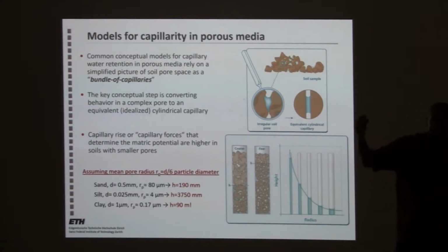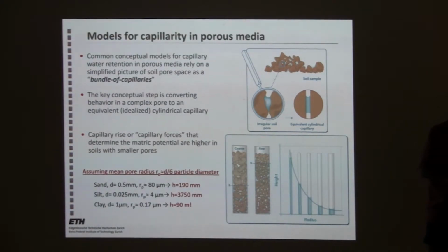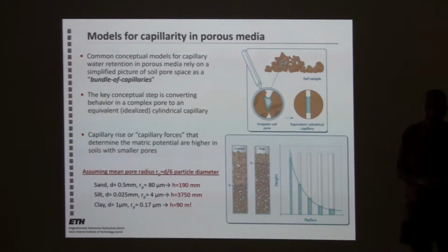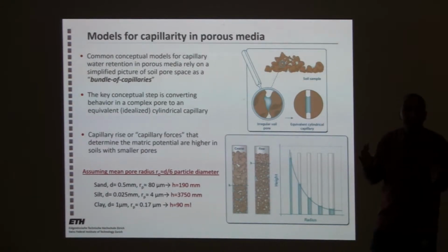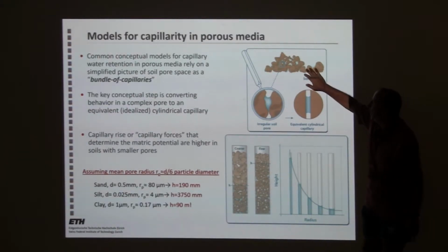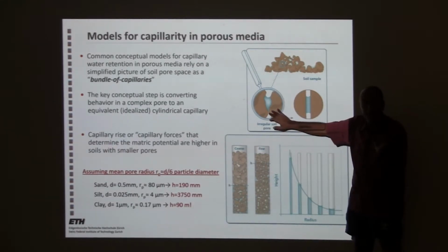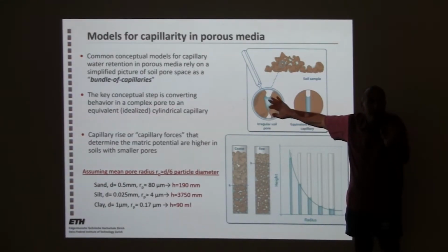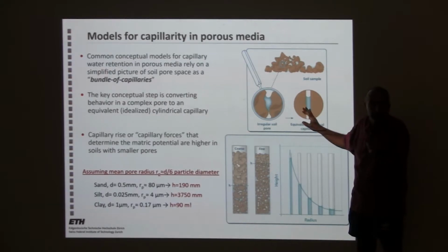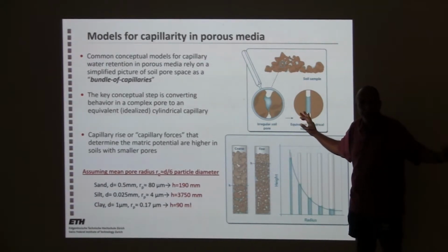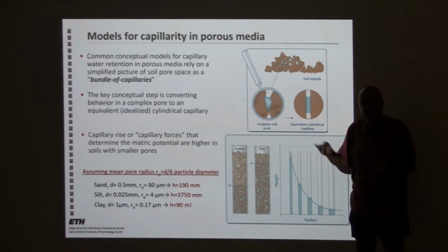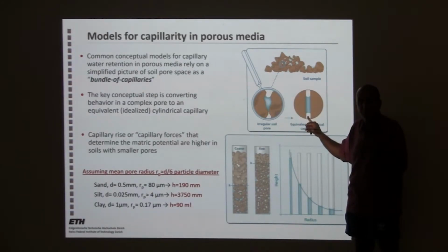So capillary rise is basically a culmination of the surface tension, the contact angle, and the curvature of interfaces, and it is fundamental to our understanding of how water is held in unsaturated porous media. So much so that we take very complicated pore spaces and conceptualize them as if they were some equivalent capillary, and all our science, all the stuff that you heard earlier this morning from Reen about hydraulic conductivity and so on, is based on this conceptualization.